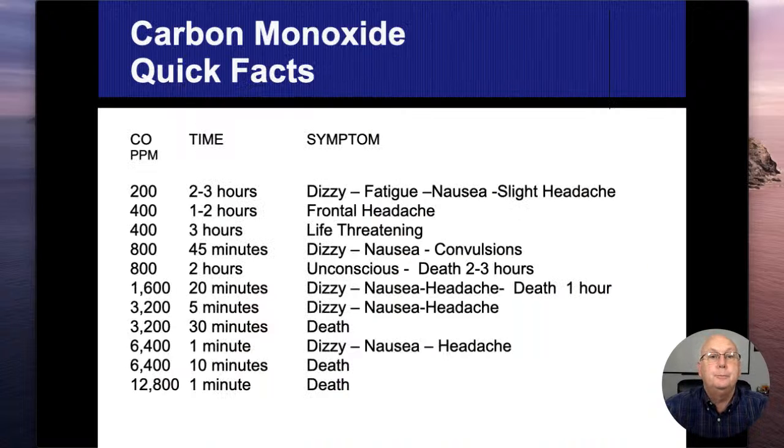All right. So carbon monoxide is serious stuff. It doesn't take all that much. When we're measuring these things, we're measuring in parts per million. So when we got 200 parts per million, that's a lot of parts. Actually 40, we'll get down there. That's usually when the carbon monoxide alarms start going off. And I think that's also what they call the threshold limit value, the TLV.